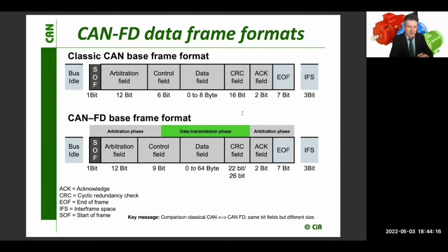It has the same arbitration phase and a data phase, which allows transmitting data at much higher speed. It can be transmitted much faster, although we have to sacrifice some bit detection capability of CAN in this case. So the bitrate switching to the higher bitrate occurs here.